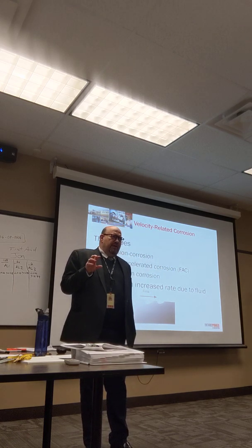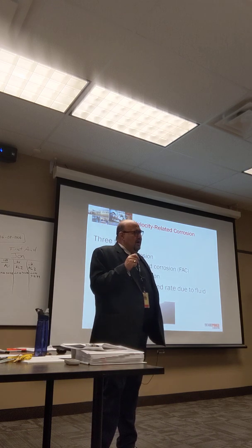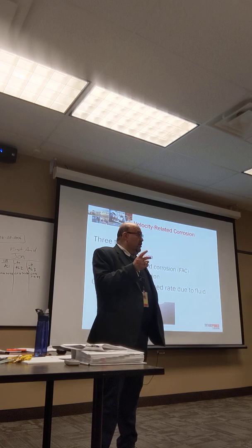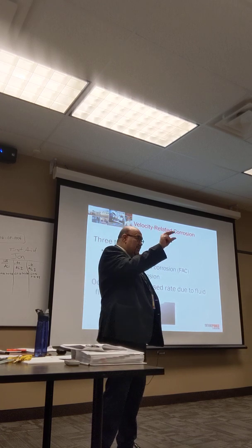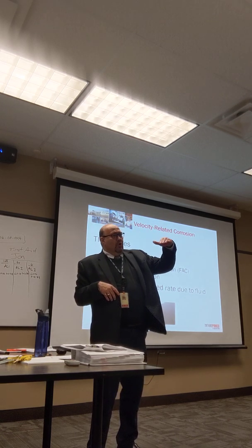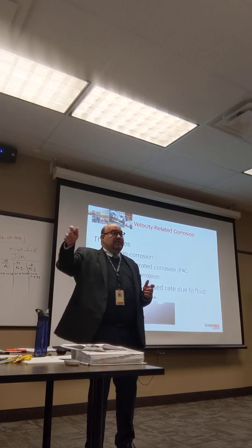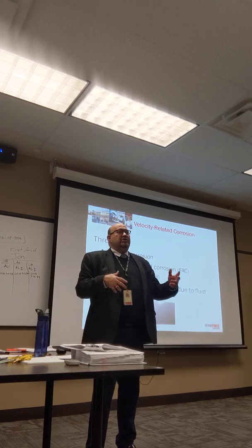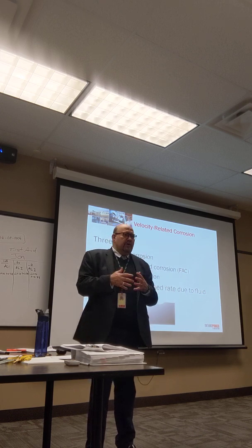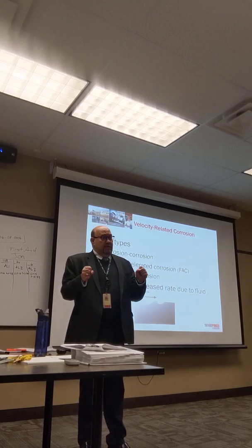So we're focused a lot on preventative maintenance, taking measurements of the system, and actually proactive replacement. So sometimes in certain areas you go, you measure with a probe, and then after 2-3 measurements, you're able to project your thinning rate or your wall loss rate further. And you're saying, well, how can I change it? Perhaps now, or maybe can I leave it for another outage or two, things like that. So this is something we should be proud of. We're doing that here at OPG.